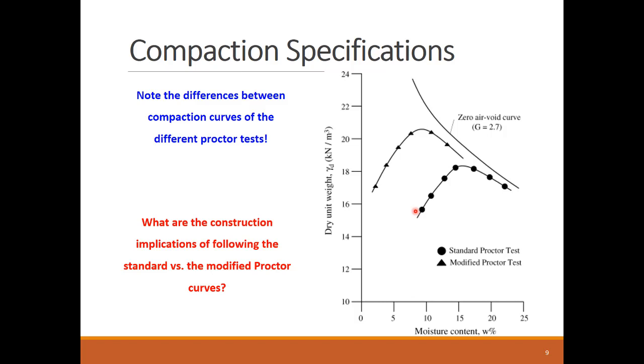the site. Modified Proctor test sets a higher standard for compaction quality by increasing the possible maximum dry density, but that will require heavy, strong compaction equipment to deliver the required power. On the other hand, the standard Proctor test will allow using smaller compaction equipment, but will probably result in the need to apply more water to the soil to reach the larger optimal moisture content.